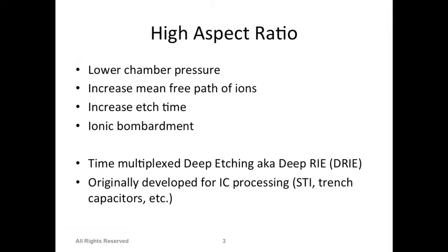So it's anisotropic because it's etching in one direction more than the other, and that's why we also want to go through crystal structures. I think we didn't discuss it in the class, but there was a lecture which I uploaded, where we briefly talk about the crystal structures and give you an idea of what it means when I say 100. So at least now you know, okay, 100 means the crystal structure in a certain direction, in X direction or Y direction, right? So that was the whole goal, to give you some background on crystal structures.